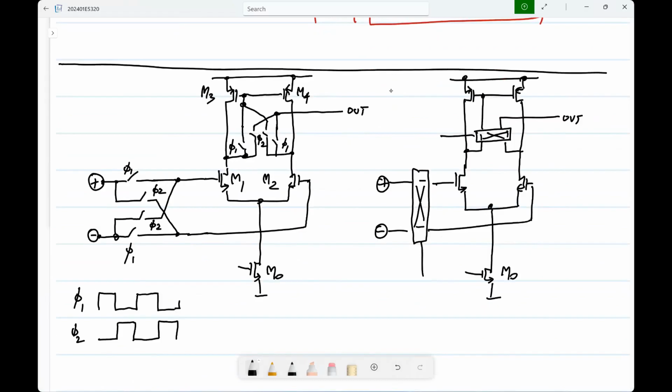Okay. And usually a control is shown like this, some phi, but you have to also be careful while operating the switches. This phi 1 and phi 2 cannot be simultaneously on. If they are simultaneously off for a short while, it may be okay. But if they are on, what happens is these two inputs get shorted to each other. Okay. So that should not happen. Right. Same for the output side. Typically, there will be constraints like that also.